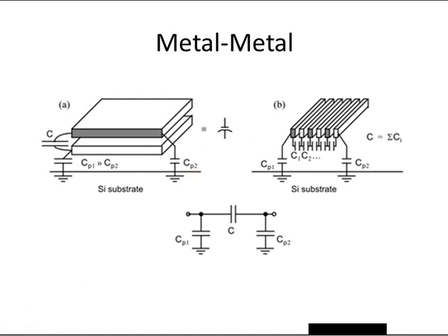Another general point, regardless of what type of passive devices we're talking about here, whether it's capacitors or resistors, is that just as with transistors, whenever matching is important, we're going to want to realize our passive devices made out of a sort of fixed library of unit-sized passive devices. And we're going to want to make up all values that we need in a circuit out of either series or parallel combinations of these unit-sized devices.